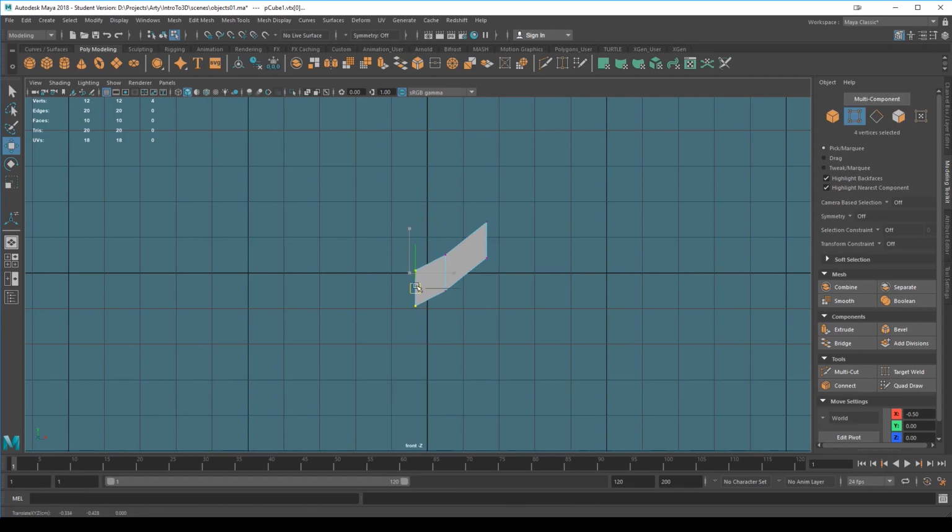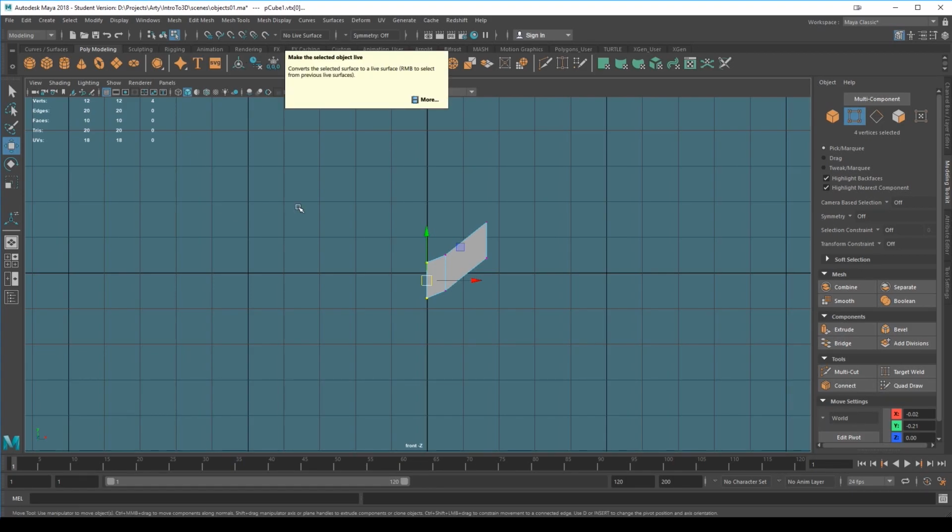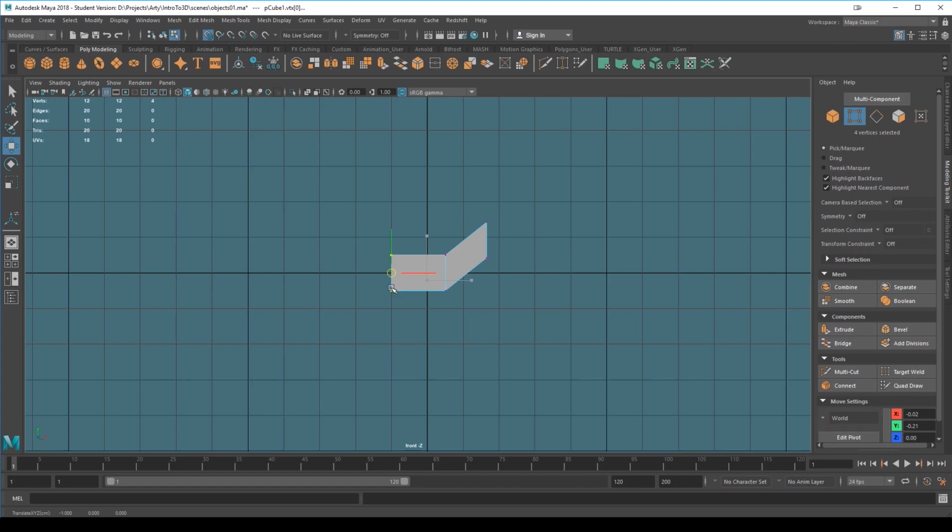What I want to do here is start snapping this to the grid and use the grid to my advantage. So if your grid is turned off, make sure you click on this button here, the grid, in the viewport, which lets you see the grid. And these little magnets, they're icons of magnets, are called snapping. So this snaps the selected object to what mode we're choosing. And the very first one is a picture of a grid. So with this turned on, and you'll know that it's turned on, or some sort of snapping is turned on, because you've got a little circle. Notice that this has changed from a square to a circle. It's just a little sort of visual reminder. And with it turned on, it now snaps.